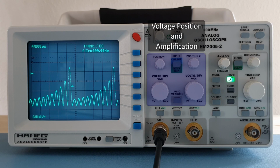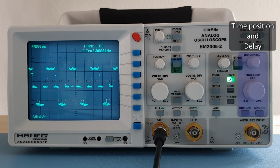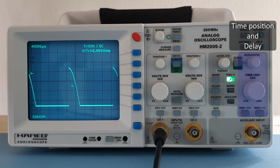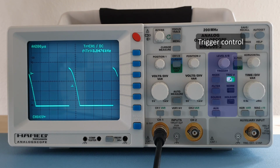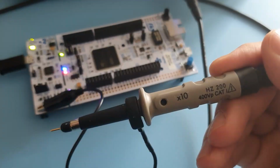With these controllers, we can select the position of the signal vertically and also the amplification, that is, how many volts per division. With these controls, we can select the position of the signal horizontally, and also the value of each division of time, in this case 200 microseconds per division. The trigger control is kind of an advanced control, but it means the synchronization of the signal with the oscilloscope.